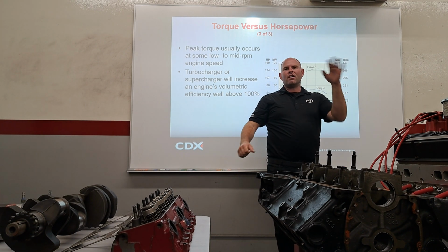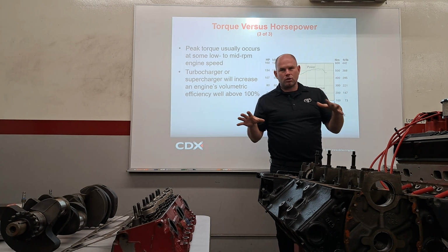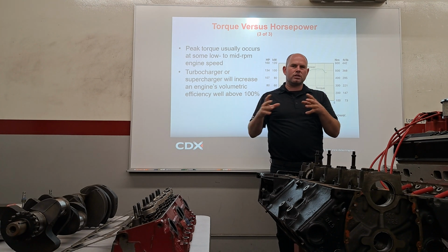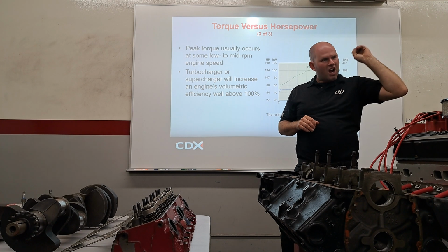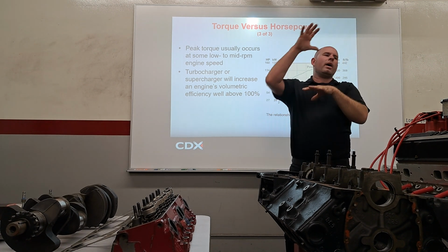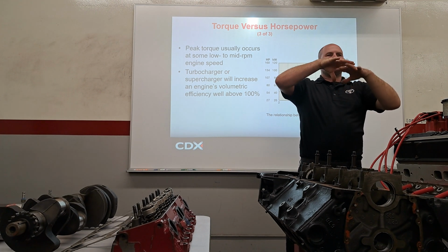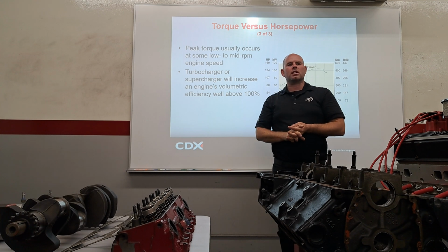Cool? Then the valve closes, then it compresses it. Now that's a whole other concern, depending on what the compression ratio is and the rings and how stuff is sealing. Cool. But then we're gonna light it on fire, and we're gonna burn it. The more air you had on that intake stroke, the more fuel you can add, the more power you're gonna get. That's efficiency. That's gonna be pretty efficient.